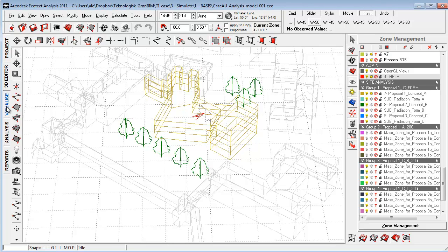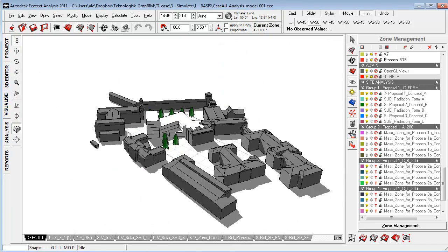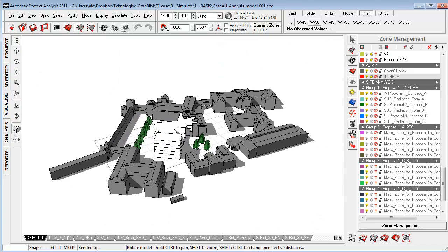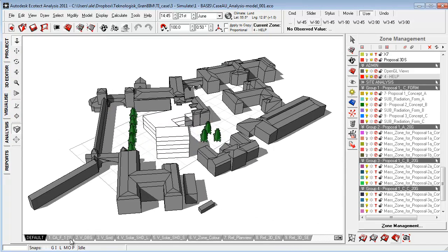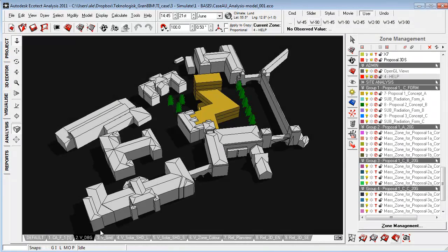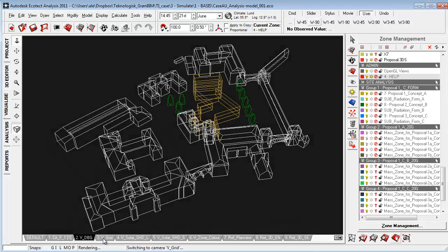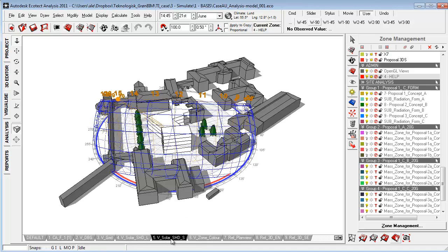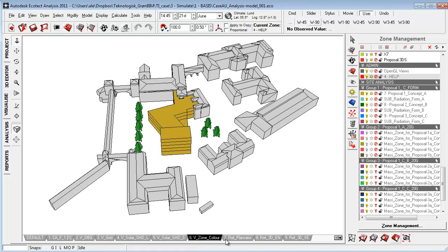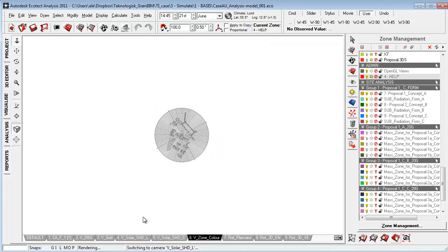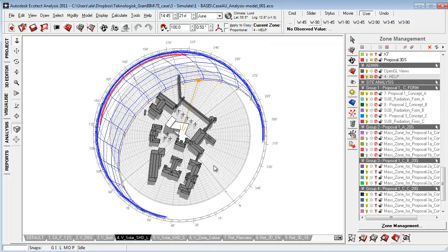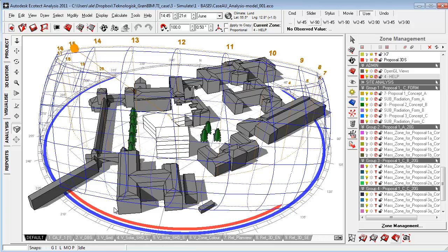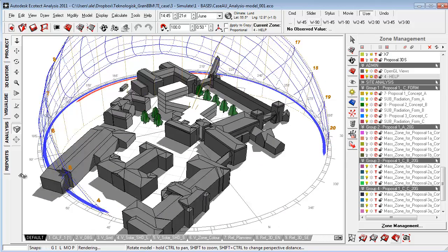So you can really do a lot of great things with this tool, both visually and also with calculation functionalities. And a great way to visualize is here in the Visualize tab. Here you can set up different kinds of functionality and ways of looking at the model that you can save out in these different camera views, and those are actually also materials that you're working with. So if I want to see the zone color, or I want to have my sun path with a compass on my surface grid here, or whatever, I can quickly customize that for the application and set up those things.